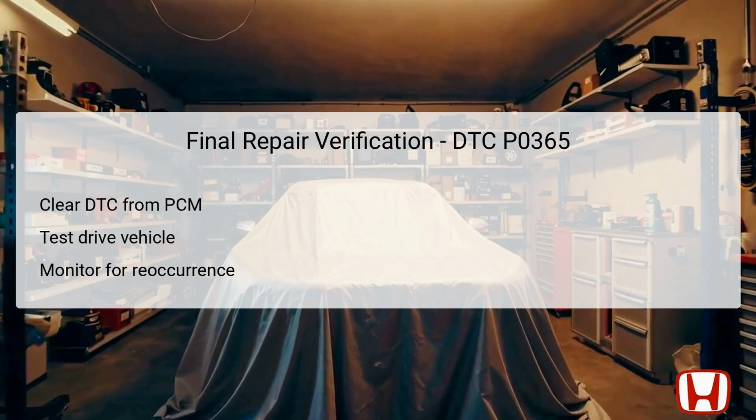Once all repairs and replacements have been completed, it is crucial to verify that the vehicle is functioning correctly before concluding the service. Start by clearing the DTC using an appropriate diagnostic tool to reset the PCM. Following this, conduct a test drive under various conditions to ensure the vehicle operates smoothly and that no warning lights reappear.